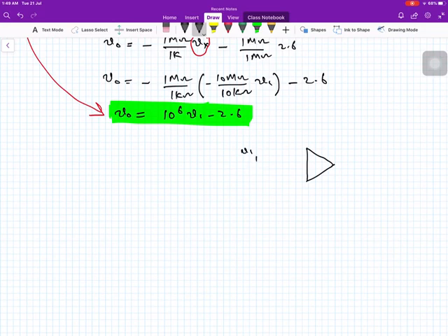So V1, this is positive with respect to ground. This is connected to the non-inverting input, and from the inverting input we have a resistance of 100 ohm, and we have a resistance of 10k, and over here, let us call it Vx.